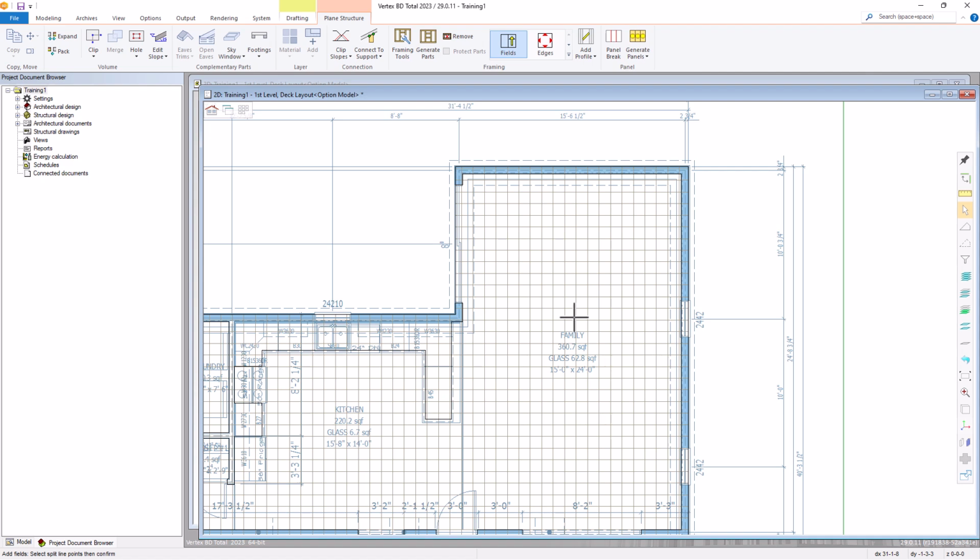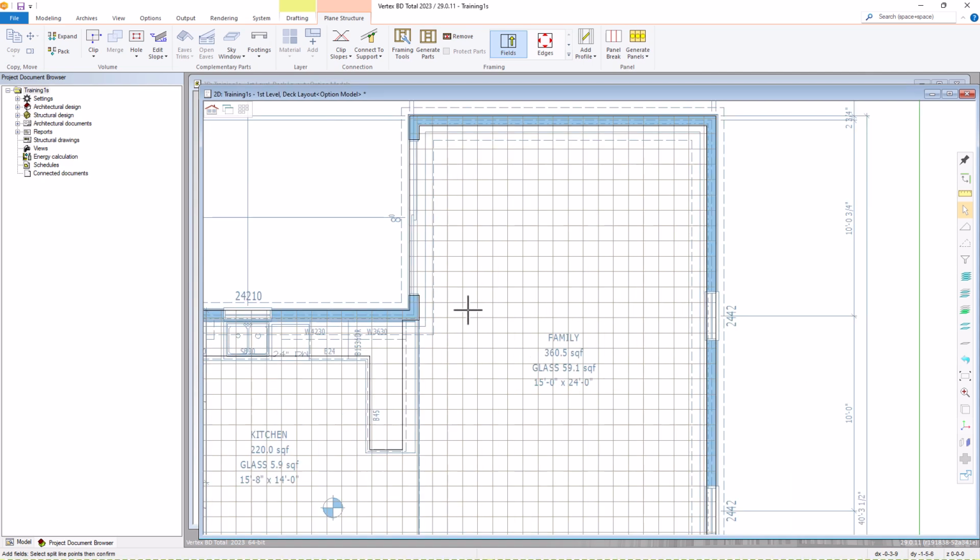We will change the joist to run horizontally in the new field, while the rest of the joist will run vertically in the original field. When adding a split line, the start point must be located on an outside volume edge or corner. The end point must also be located on an outside edge or corner. This split will be very simple. We'll start from this corner and run it across horizontally.